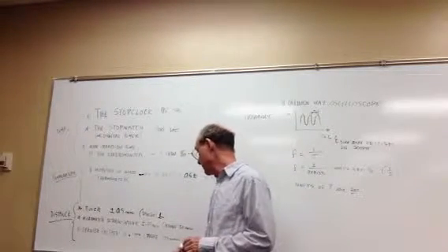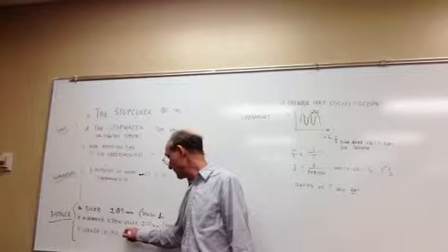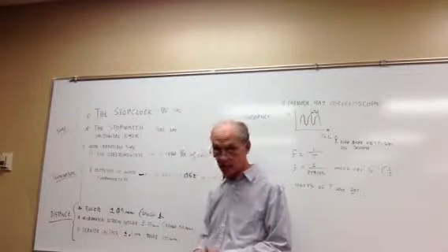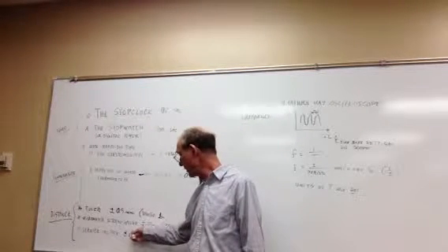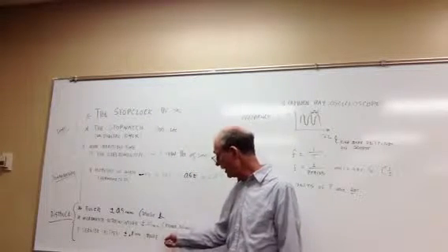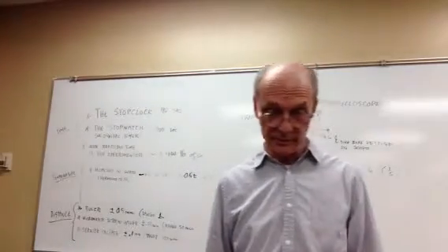And then, if you're interested in even more precision, then you might want to consider the vernier caliper, which is another device that measures to plus or minus 0.1 millimeter over a range of about 100 millimeters.